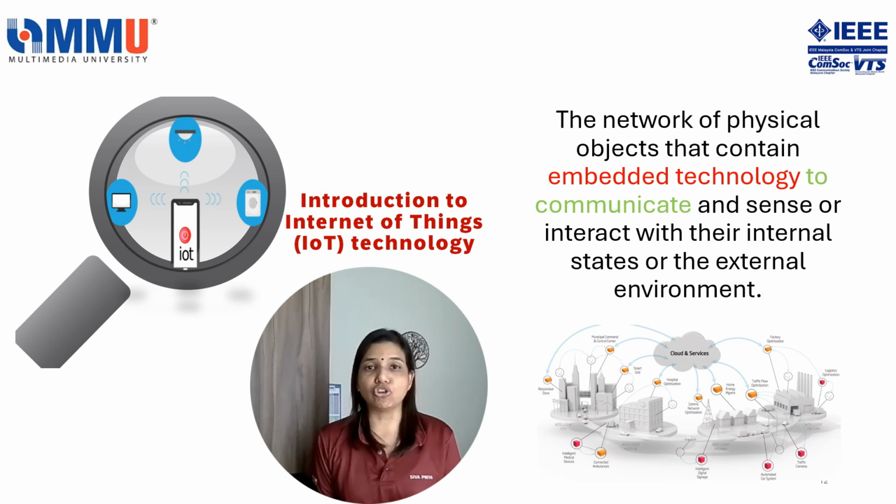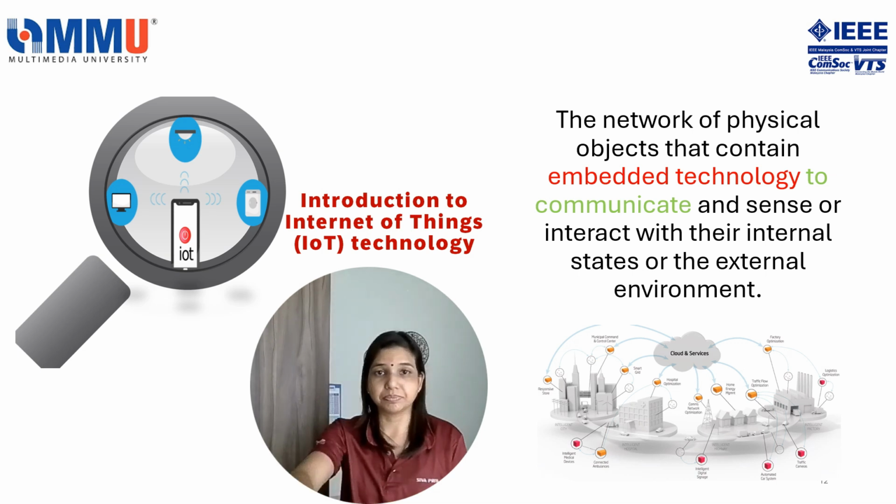When the temperature drops to 23 degrees Celsius, the sensor will detect this drop in temperature and inform the microcontroller. The microcontroller will then take an action because it has been programmed to ensure the room temperature is always 24 degrees Celsius. This way, it will interact with the internal electronics of the air conditioner and instruct it to go back up 1 degree Celsius so that the room temperature is maintained at 24 degrees Celsius.